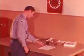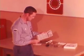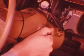Now, let's talk about diagnosing specific problems. Here, we'll use the operating conditions shown on the drivability checklist: engine cold, engine partly warm, and engine warmed up. Under engine cold, let's begin with starter cranks, but engine won't start. First, glance at the gauge for indication of fuel in the tank. Then try the recommended cam starting procedure. If the engine fires a few times but does not run, it may be flooded. Hold the pedal down all the way while cranking and do not release it until the engine starts.